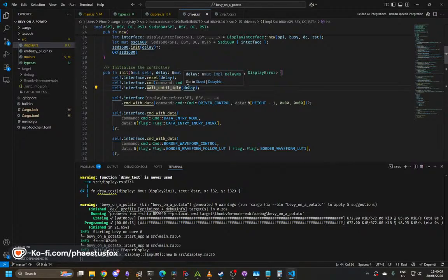Okay, so wait until idle. So I'm assuming, did it state? So top one's busy. So if I say busy and I don't want to touch there. Idiot. Oops, that's continuity. Well, apparently busy's connected to ground at the moment, so that's fine. Out of curiosity, is busy connected to ground normally? I'll measure voltage, thank you. -3 volts. Oh, that's probably why. Okay, the busy is high at the moment, which makes me think we're stuck here.